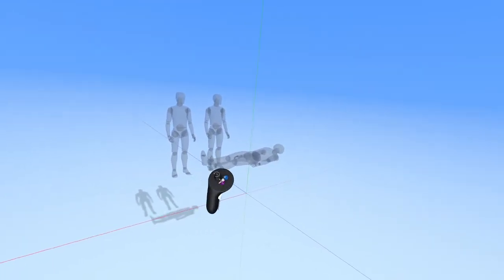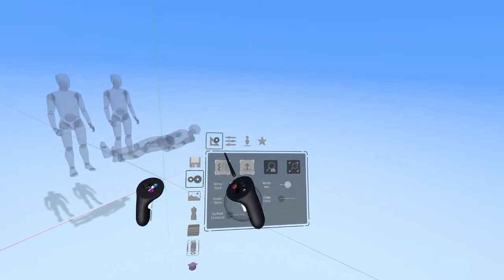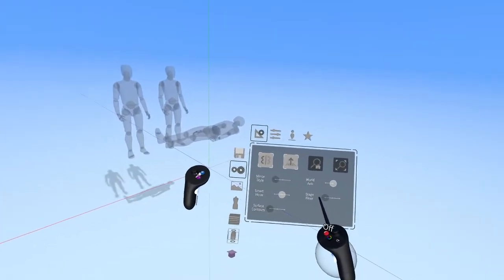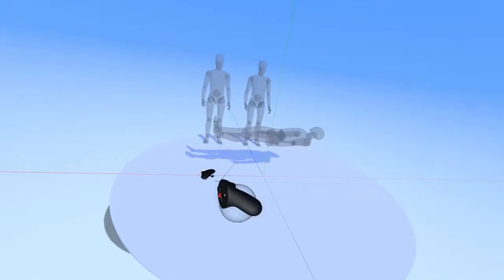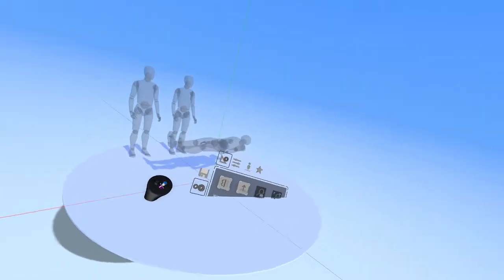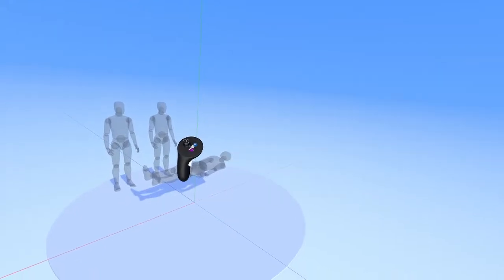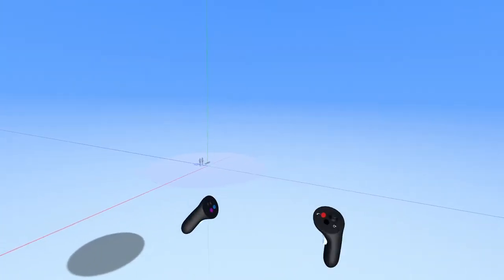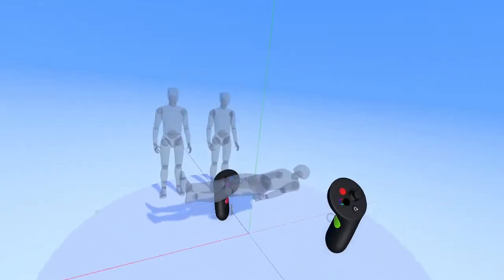We can start sketching. So actually, before we start sketching, I'm going to go to Settings, Sketching Aid, and turn on Stage Floor here. So you have a couple of selections here. You can have it off all the way to the left, a rounded stage floor, and a square stage floor. And this is just going to give me something to build to so that I know how things are going to interact, where the wheels are going to be, all that kind of stuff. All right, so now that I've done that, I can press the blue menu button, get rid of that. And the nice thing about the stage floor is it auto updates. So if we zoom out here and we keep creating geometry, it's going to auto update and expand that stage floor to fit the context of what we're designing.